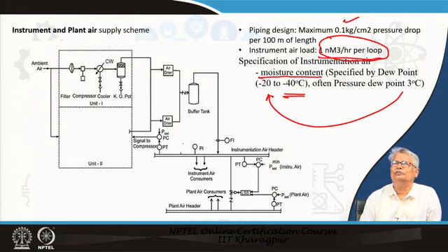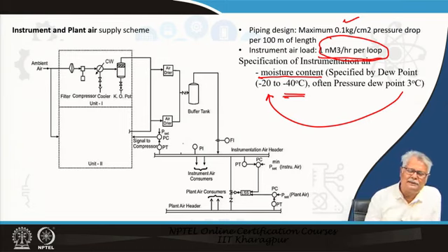Obviously, you do not go for the exact size of your pipe diameter, you go for the next commercially available size. In the system, if you see, the ambient air passes through a micron filter, which is basically a felt filter. Then it goes to the compressor. Then after compressing, it is cooled with cooling water. Naturally, you have a drain for whatever moisture condenses in this particular vessel.